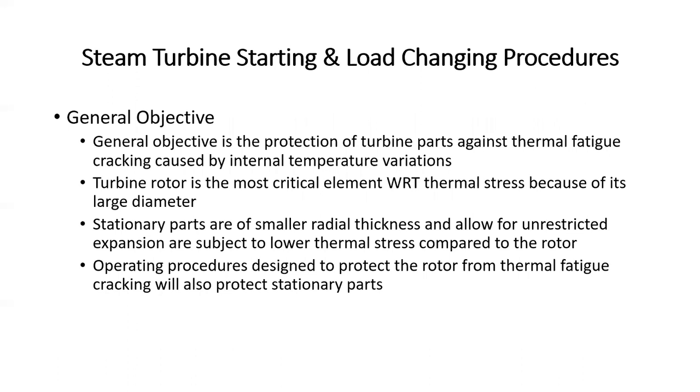Under general objective, what we want to do here is to protect the turbine parts against thermal fatigue cracking caused by internal temperature variations. The turbine rotor turns out to be the most critical element with respect to thermal stress because of its large diameter.